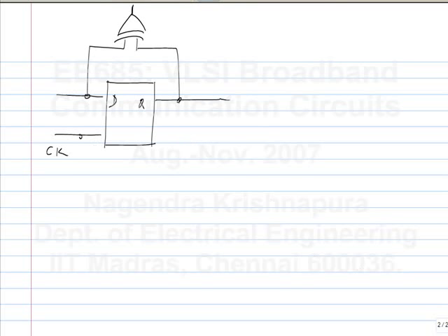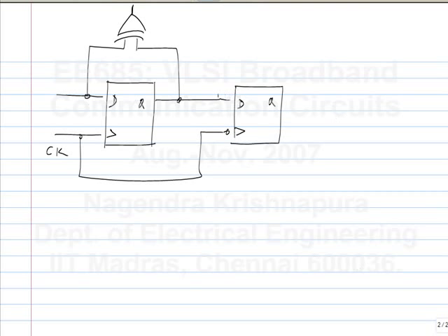So the idea is to use another clock, and here we rely on the 50% duty cycle of the clock. So this is the rising edge, this is the falling edge triggered flip flop. And we do this. Now there are several practical things that make this a good phase detector. You are getting this pulse, the subtracting pulse, in exactly the same way as you do this. So all of the non-idealities, the weirdness in the shape that you see in this pulse will also be there in this. So the cancellation will be better. There may be other ways of getting a half period pulse and trying to subtract it, but in that case, the pulse shape may be slightly off, and you will have a bit of a problem.